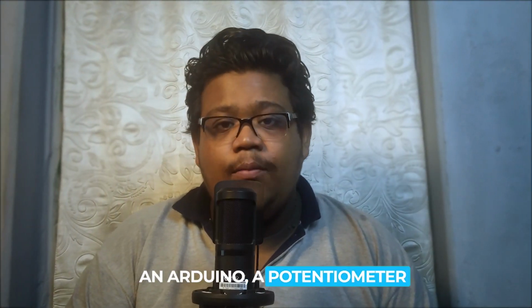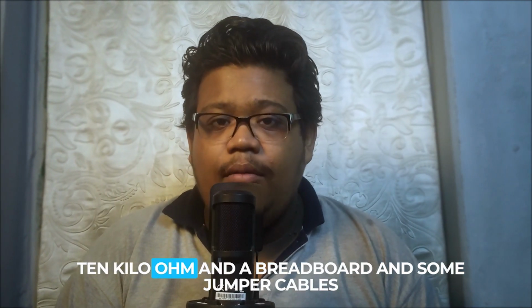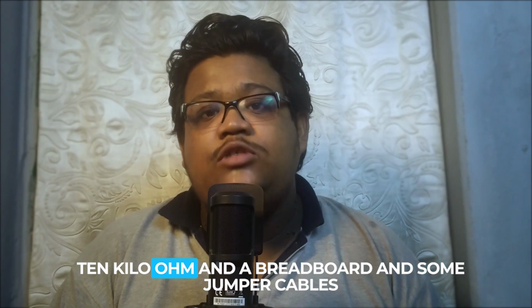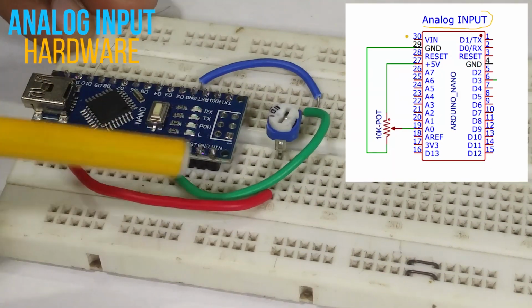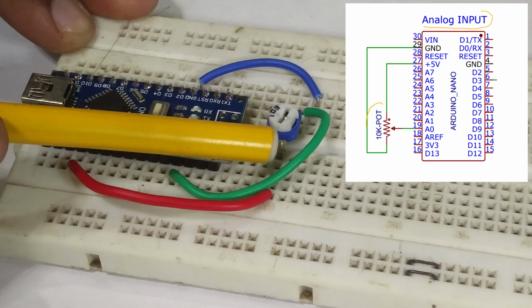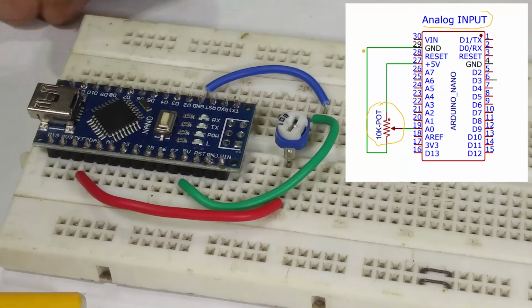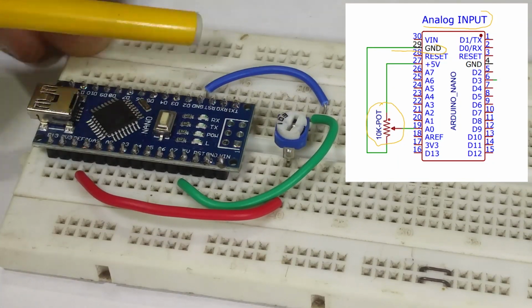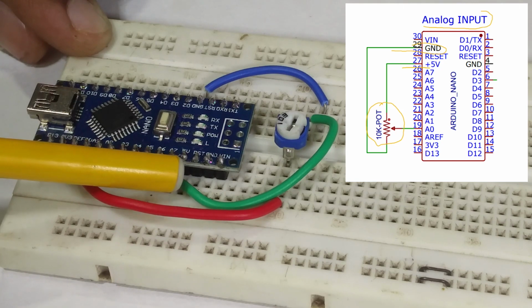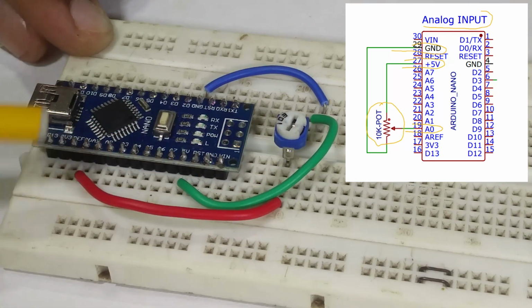So for doing this experiment, we need an Arduino, a potentiometer, the value of the potentiometer is 10 kilo ohm, and a breadboard and some jumper cables. So here is the circuit of our analog input. I am using a 10 kilo ohm preset as I don't have a breadboard friendly potentiometer, and one end of the preset is connected to ground, another end is connected to 5 volt, and the center pin is connected to the A0 pin of the Arduino.